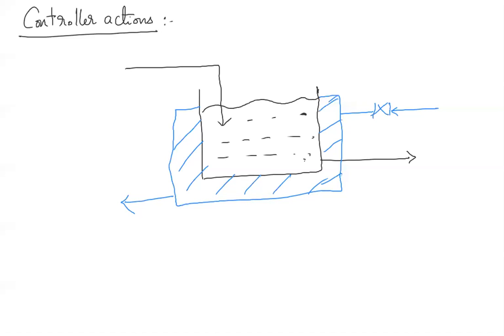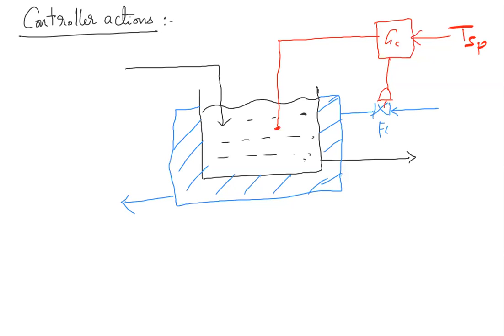Now you have the instrumentation, measurement, temperature set point. Clear? Now, suppose let's say, what is this valve type? This should be fail to open.